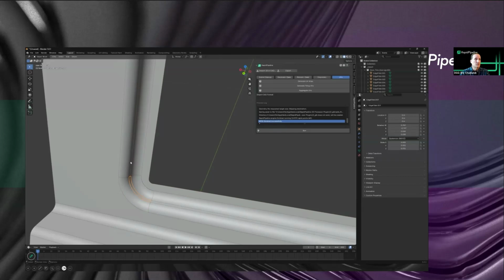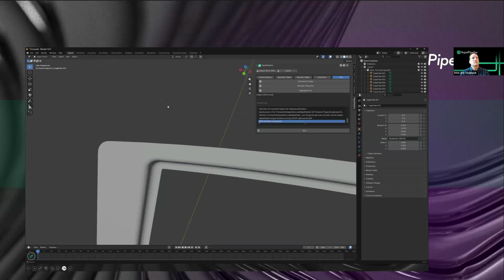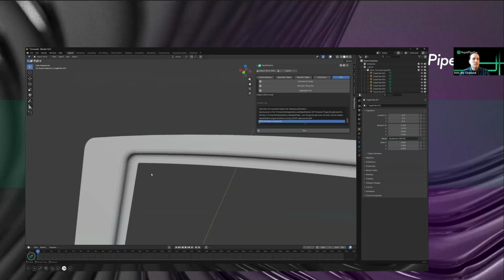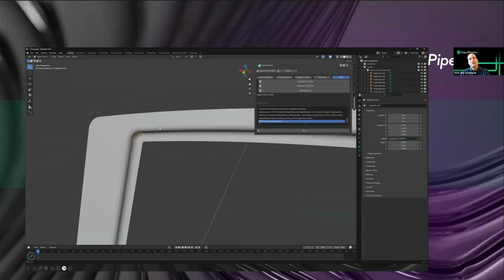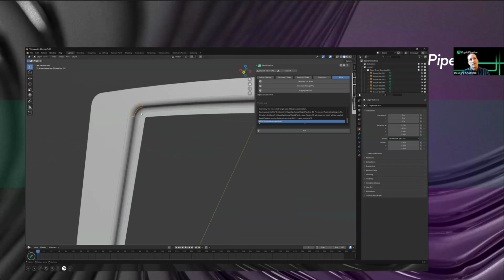In order to generate all this fine curvature, you need all these separate surfaces. So without sewing, you get all these different parts, which may be what you want, but in general, as a 3D artist, I want all this stuff taken care of so I don't have to deal with all these little parts and then have to patch them together.